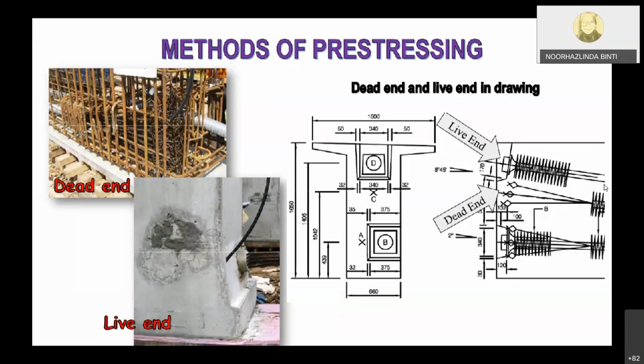I think so far I haven't come across them considering more than that, up to the yield strength. No, never. Because when you design prestressed concrete, there are certain things that we need to take into consideration. Number one is that we design only in the range of the elastic limit. So good question from Wen Xiang.